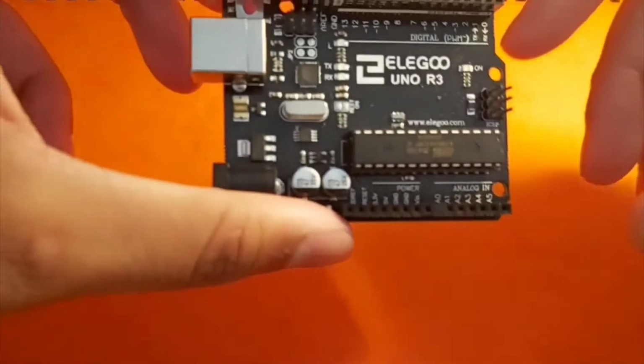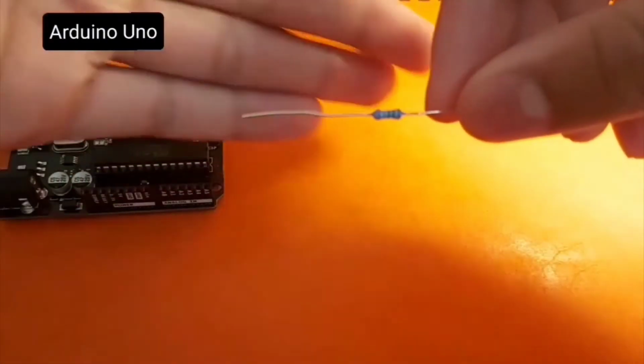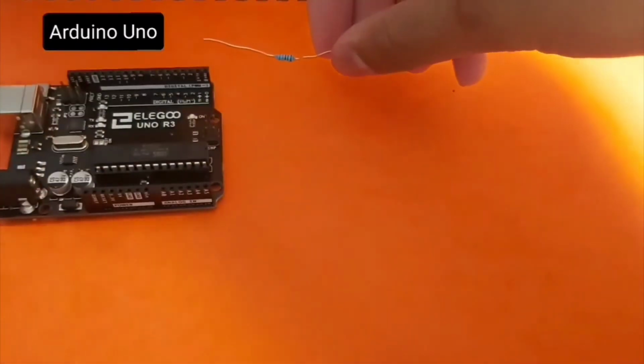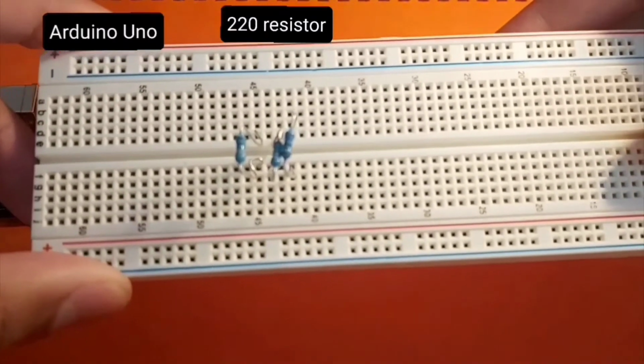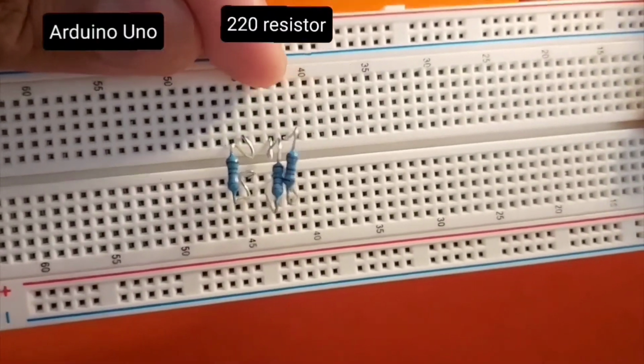So before we start our project, you'll require a few things. First, you will need an Arduino Uno board. You're also going to need a 220 ohm resistor. You're going to need 3 of them. So I'm going to use a breadboard, and I have attached the resistors on the rows 42, 43, and 45.